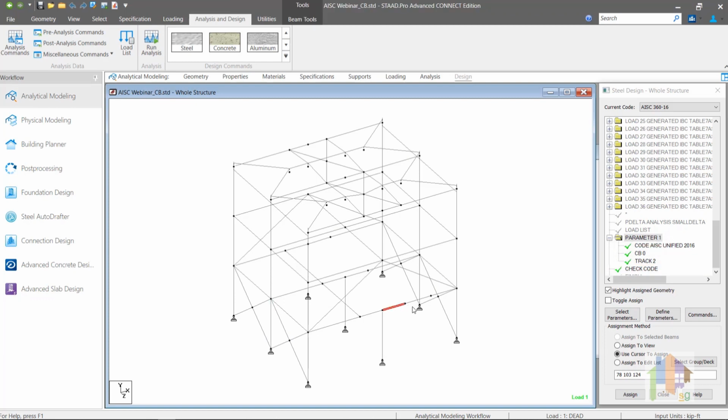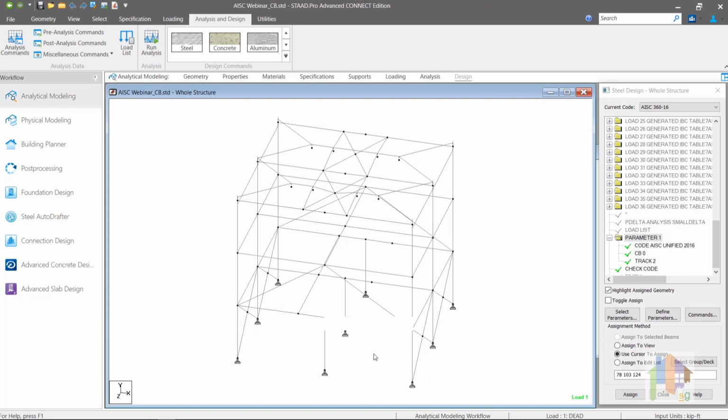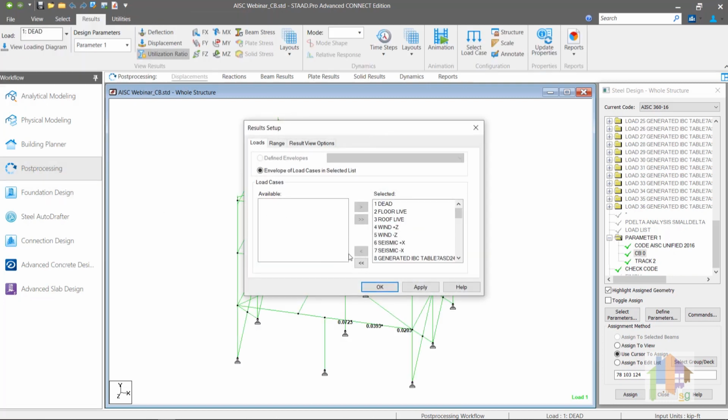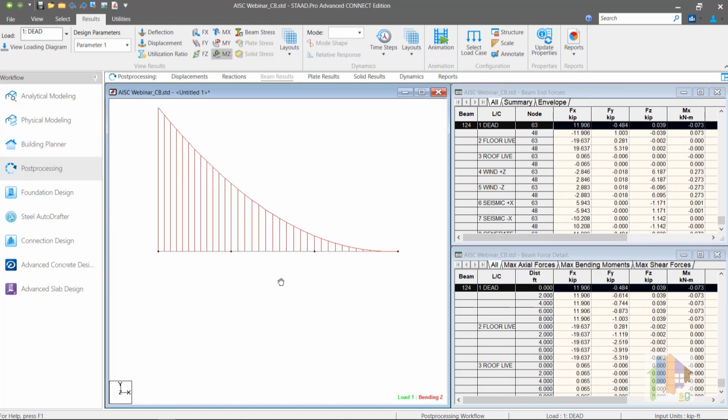Now consider these members. The member between the columns is divided in 3 segments, and there is no connecting member at an intermediate location. So there is no restraint to the top or bottom flange, and hence the unbraced length should be the total length between the columns. But if you assign the CB value as 0, the program will consider the unbraced length as the member length, and on the basis of the moment values at different locations of the individual member, this CB factor is calculated. As the unbraced length is not equal to the member length, this causes some problem.